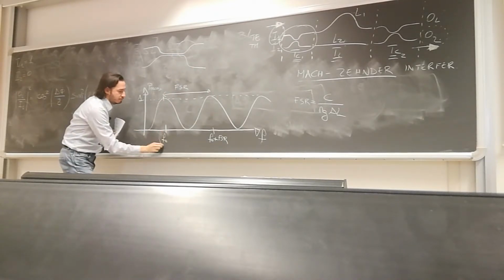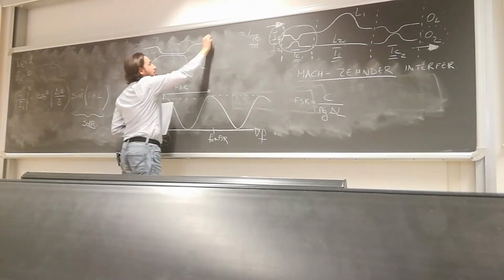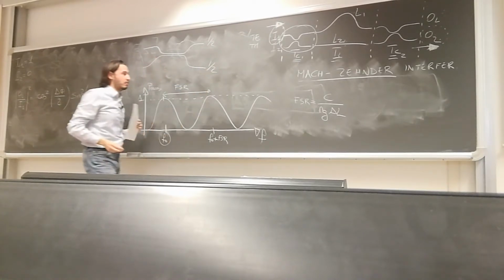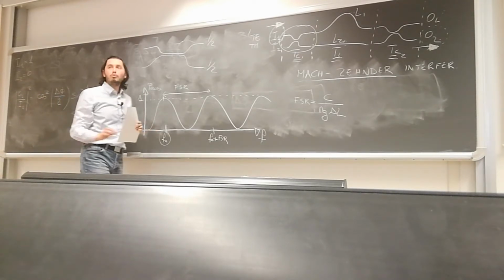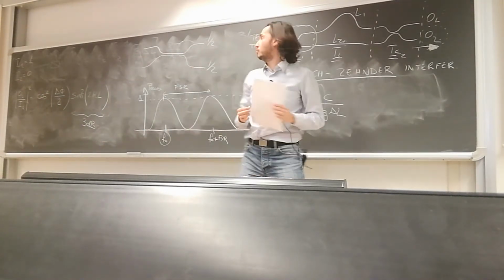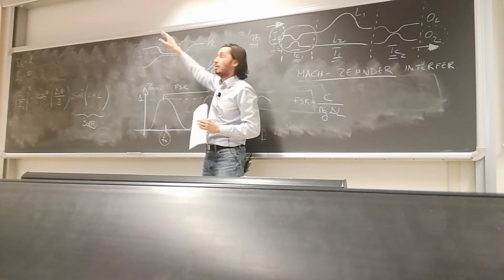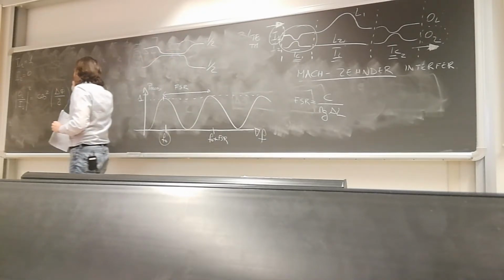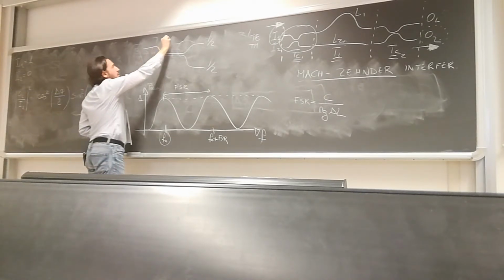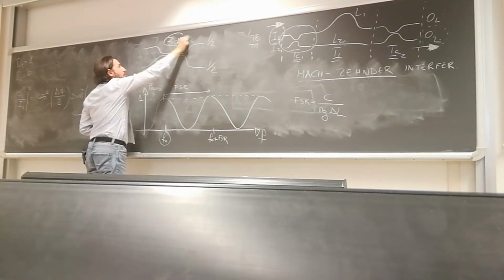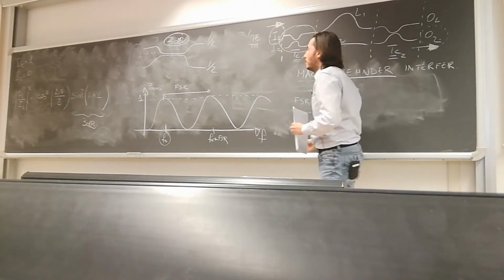at this frequency, if I'm a good designer, I do it in a way that 50% of the power goes here, 50% of the power goes here, okay? At this frequency. Then, what is going to happen if I change the frequency? So this is realized, it's fabricated, so I cannot change anything more of this. But I want to use it at a different frequency. Okay? So is this 3 dB splitting maintained at any frequency? The answer is no. I already told you. Why?